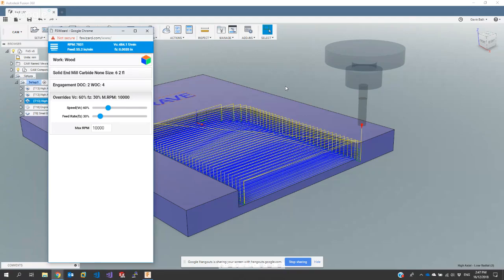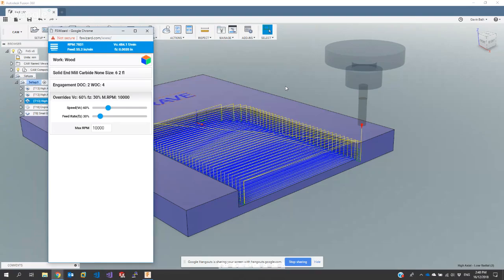Also looking at what's coming off the tool, and looking to see if it's really fine dust or if you're actually creating little chips. So the little chips quite often look like, I suppose, fingernails in a way. Would that be a good description? In materials like plastic and metals, yeah, absolutely. In timber, you tend to not see it. Well, I suppose it depends how closely you look, but the shape is a bit harder to determine. But you're spot on there.